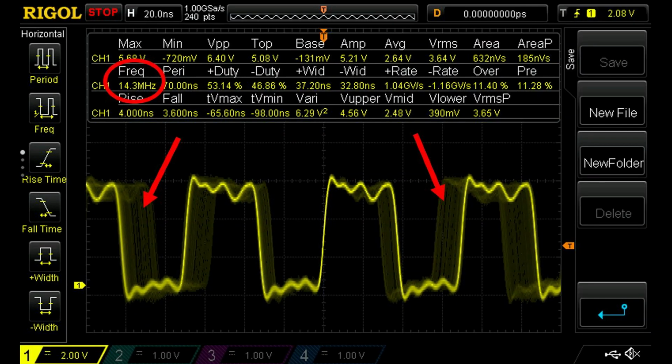As you can see from this screenshot from the oscilloscope, it was not quite what we hoped for. If you see the red ring, you can see that the oscillator is running at 14.3 MHz, so we can claim that a victory. But if you look at the picture on the scope, you can see this slight shadowing pointed to by the arrows.